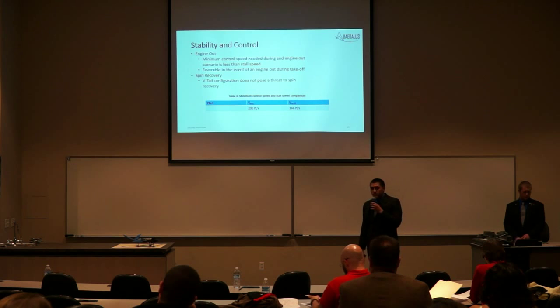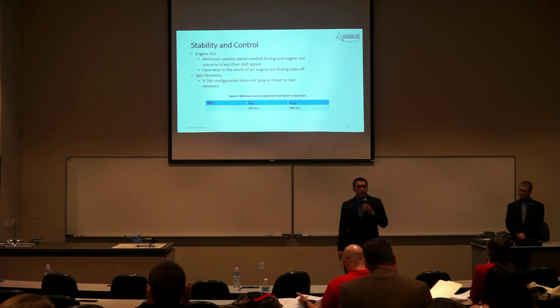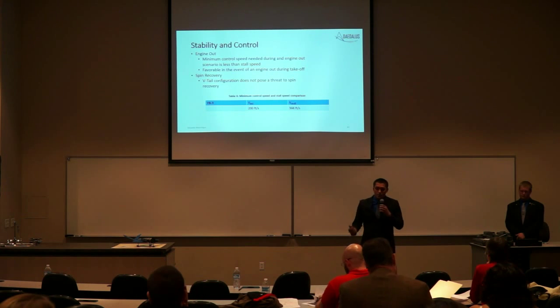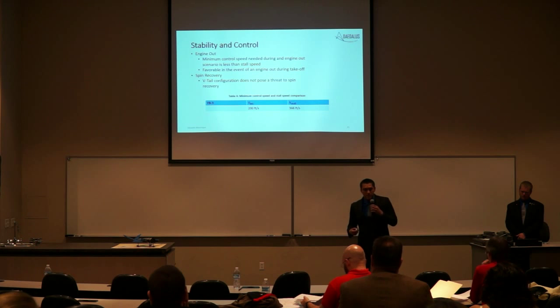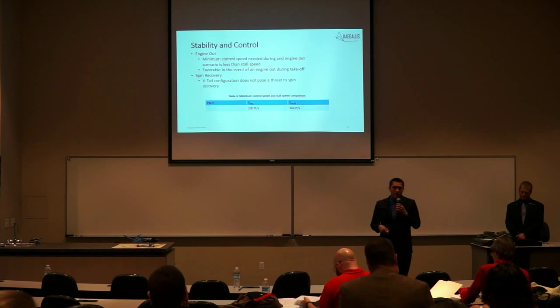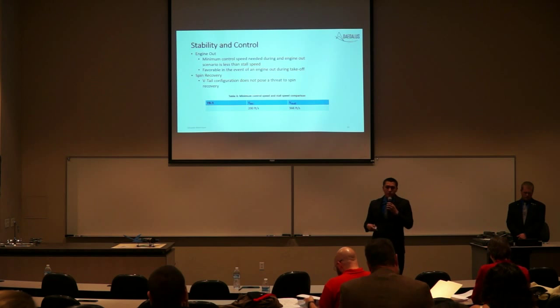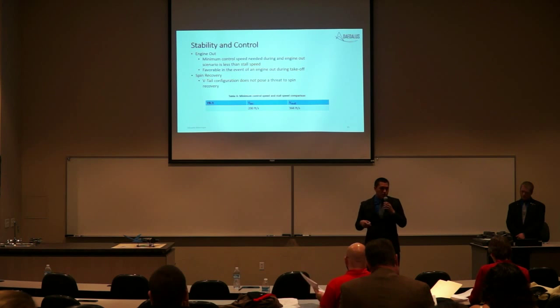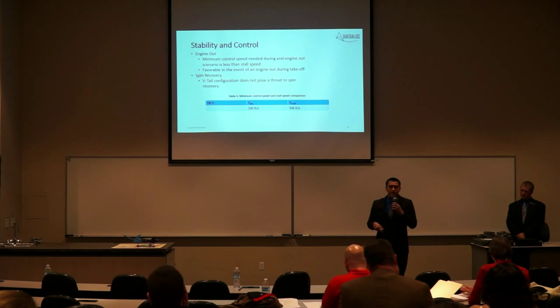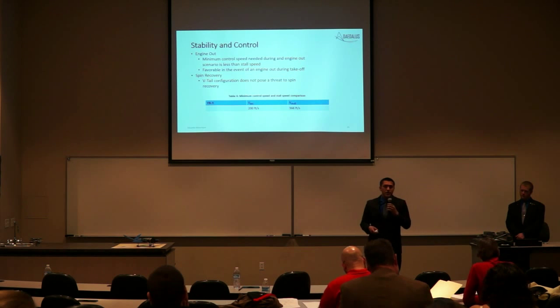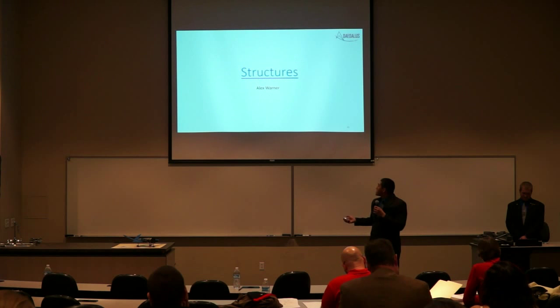As for spin recovery, since the YB-3 does not have a horizontal tail, the effective vertical tail does not get shielded by the horizontal tail. The only things that need to be taken into consideration are the wing and the fuselage itself, which may pose a threat. However, on the YB-3, only 2/3 of the vertical tail can be shielded. Therefore, the YB-3 is fine as far as the wing and fuselage shielding.